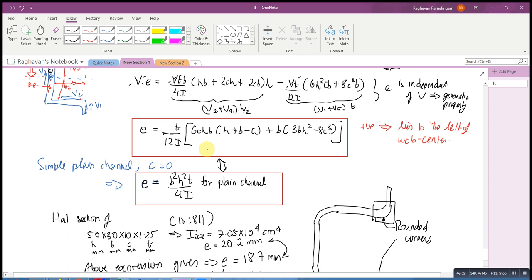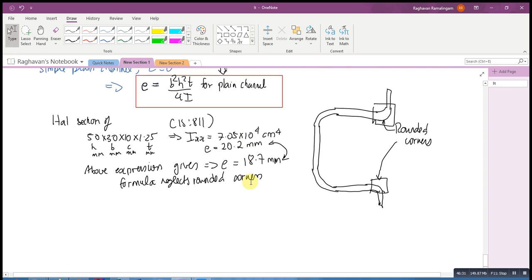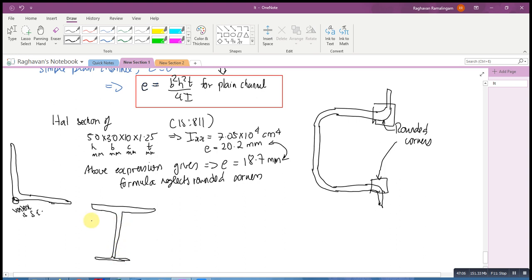Okay. And also know that for a cross section like this, your shear center will actually lie at the vertex for channels. Okay. So this is how your shear centers will be, and similarly if you have an I section like this, the center of gravity will be probably somewhere here.